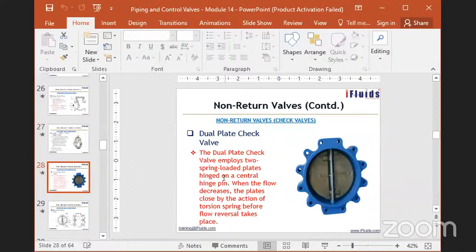Fail open, fail close, or fail locked. And these volume bottles are there for the fail locked position. Suppose when the instrument air fails, the valve is at, let us say, 60% opening. It will stay there, and you want to move it slowly to the open position or closed position. At that time the air from this buffer vessel will go to the diaphragm and act on it, either to close or open. So how they operate is, you have seen